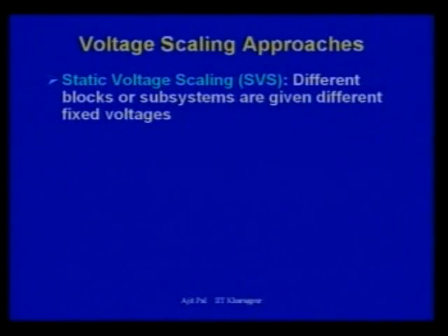And there are various approaches which have emerged. First one is known as static voltage scaling. In this static voltage scaling, different blocks or subsystems are given different fixed voltages at design time.